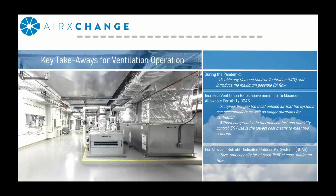All right, continuing on. You're going to want to disable demand control ventilation. Carbon dioxide is often used as a reference gas to determine occupancy, and its purpose is to minimize outside air based upon occupancy. Since most educational spaces are being used at part occupancy or no occupancy right now, you don't want the control algorithm to inadvertently lower the ventilation rate.